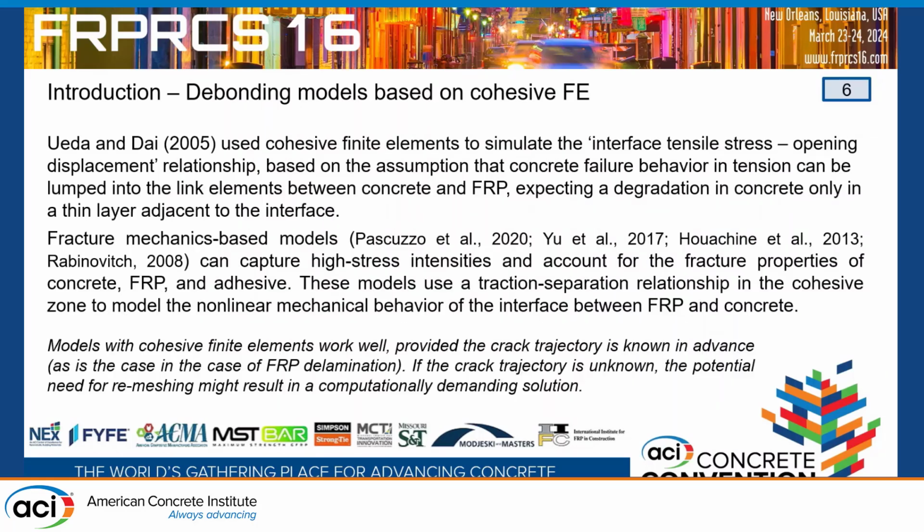Most common in the reported approaches is to use cohesive finite elements to model the interface. Maybe the first contribution, at least the one we have found in the literature, is Ueda and Dai, who used cohesive finite elements at the interface between FRP and concrete to model opening failure due to opening stresses, or mode 1.